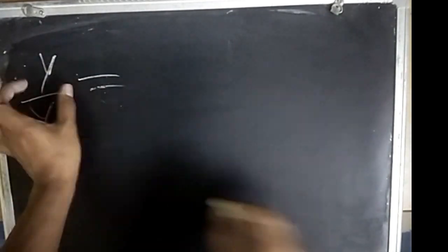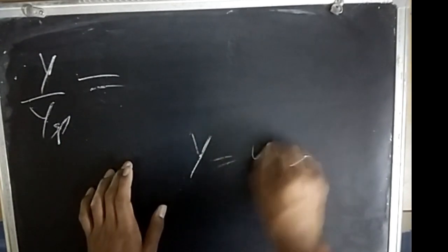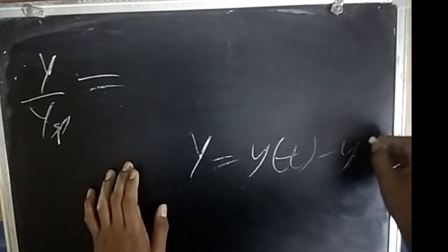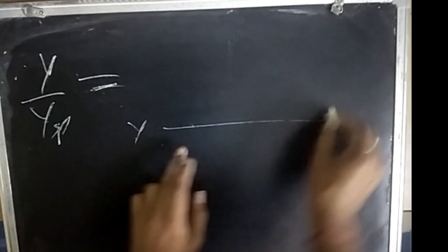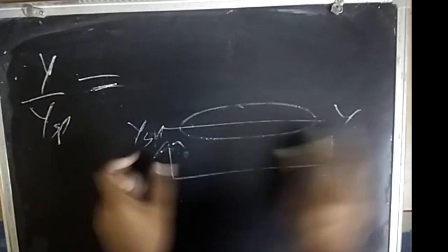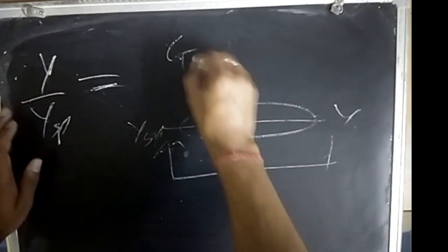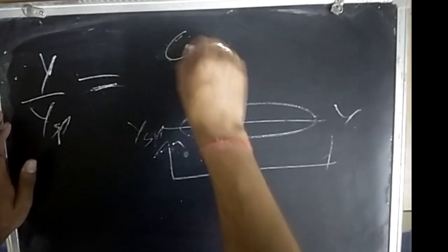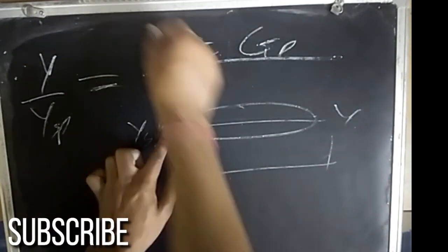So for servo, the transfer function, that is Y upon YSP, or these are the differences. Okay, Y here, I've told you, is Y of t minus Y at steady state SS. Okay, remember this because this is important. Some people make mistakes here. So first, in that particular loop, the transfer functions between YSP and Y, write them above. It could be like GC and GP only. I've taken this. If there is another transfer function here, GSP, then we'll write GSP also here. So this is the thing between these two.